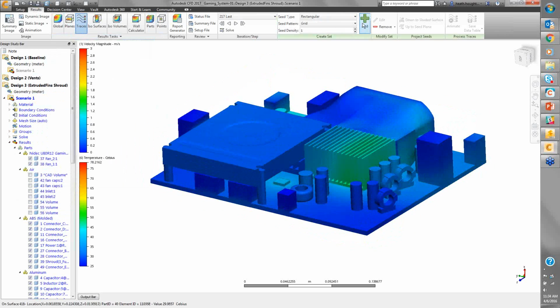So I'm going to go to traces, look at adding. First of all, I'll show you how you can add a point. So remember, they're not tied to planes anymore. Click add first. Click on a point on the model. Click another point on the model. Another point on the model. If they're a plane, I can click on a plane. The first thing it sees that's non-outline mode, so it has some color shading to it, whether it be transparent or meshed or in shaded mode, it will actually put that point there.